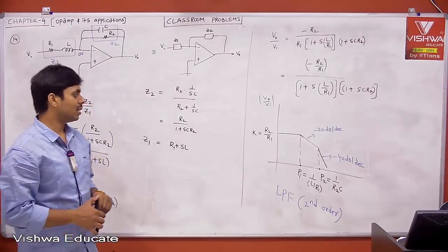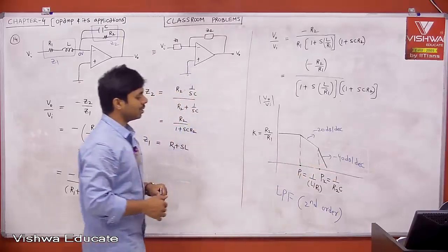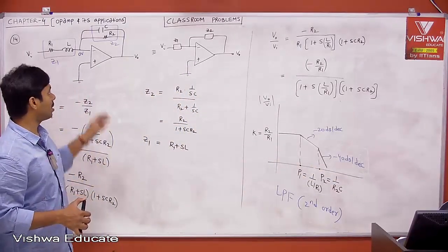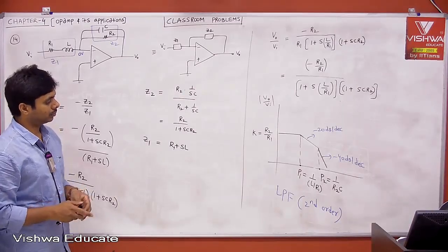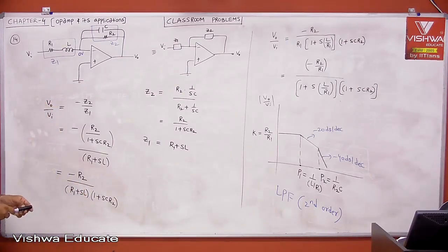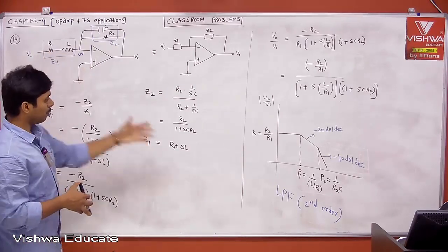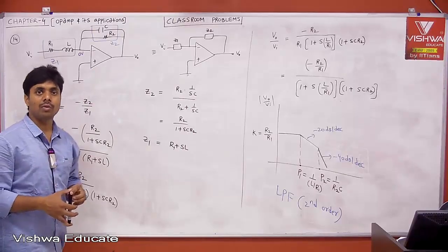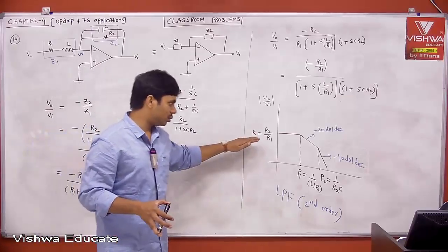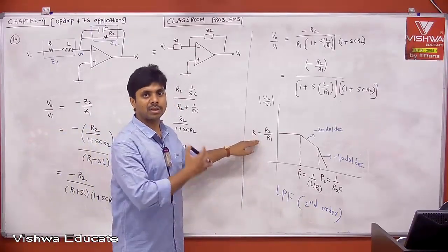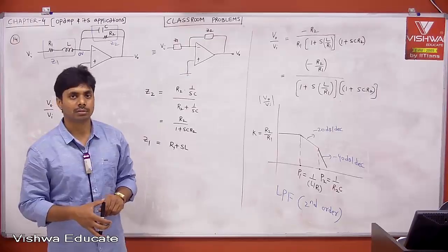That's why we need to see. Normally people say if you put P2 to the higher side, you will get it. Whatever may be, assuming that the op amp is ideal. But if you consider a practical op amp, then overall it is a 3 pole system, because in feedback we have 2 poles and the op amp is 1 pole, overall 3 poles. The system may be stable, may not be stable. That depends on the value of K. But normally if you choose the value of K such that the poles are always in the left half of the S-plane, the system will be stable.